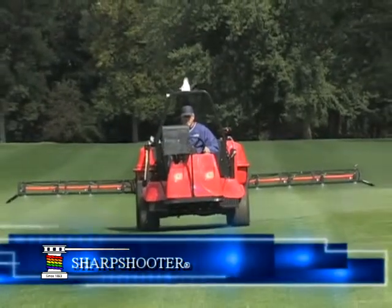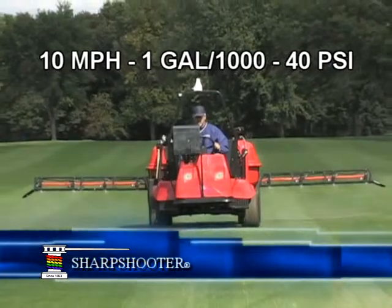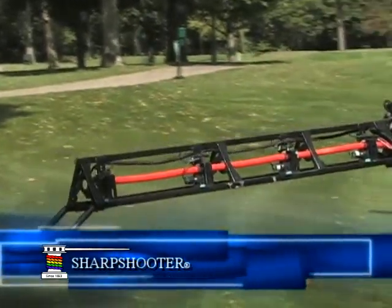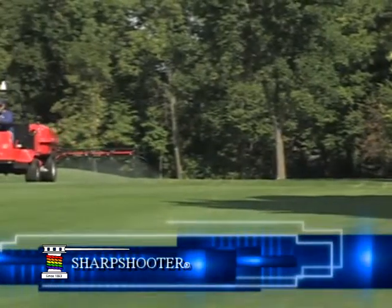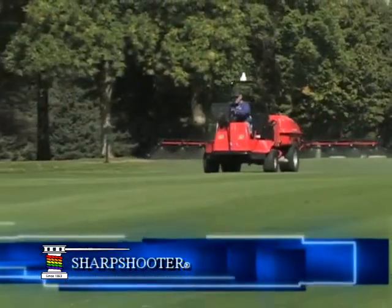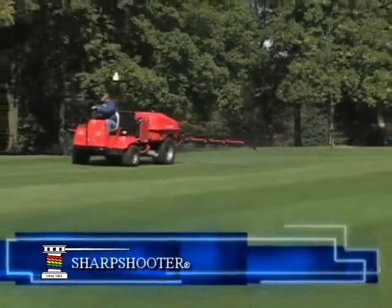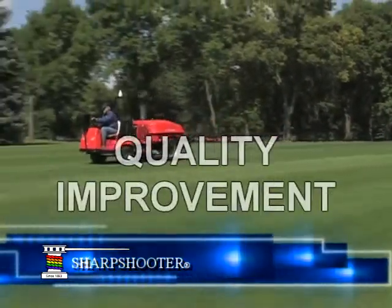Sharpshooter allows the operator the option of spraying to the maximum capability of the sprayer, typically 10 miles per hour, yet it also affords the operator the ability to slow down to 2 miles per hour when the application so demands. The amazing part of Sharpshooter's wider speed range capability is that it does so while maintaining a constant rate, a constant operator set pressure, and a constant, consistent droplet size and pattern. In short, the operator has increased speed range capability with an actual quality improvement.